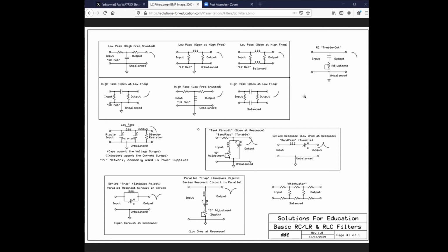Anyone know about magnetic amplifiers? No. The Bismarck had magnetic amplifiers for their control systems. What we had was actually more accurate than the Bismarck, and what the Hood had was more accurate. However, the magnetic amplifiers that the Bismarck had were stable as all get out. A lot of the systems on the Hood and some of our ships, because I was a fire control tech in the Navy, tend to get out of whack sometimes when you fire the 5-inch guns. The mag amps never did.